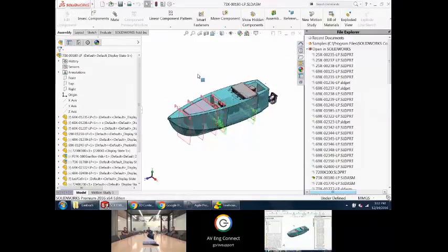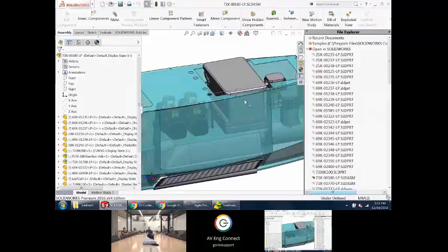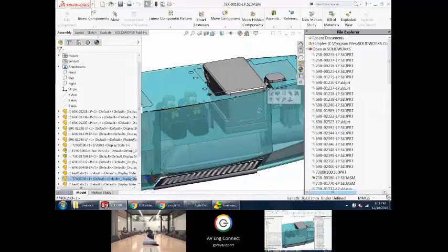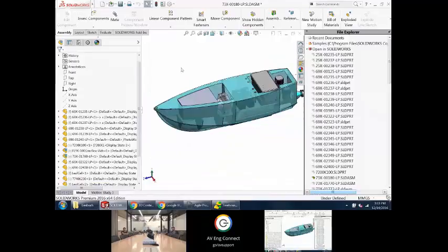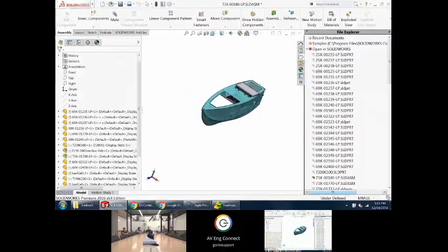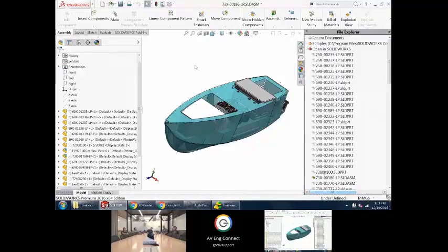Taking a look at this part. So obviously this is not large design review or large assembly mode because I can see everything going on here. Maybe I want to hide some of this stuff so I can work a little easier in here. You either hide it globally here, or you can select on something like a sketch, hide it there. Now when you hide a sketch like I just did, it actually hides the sketch in the part file. So if I open the part file, it'll be hidden there too, where this is just at the top level of the assembly. It's not affecting the parts underneath it.